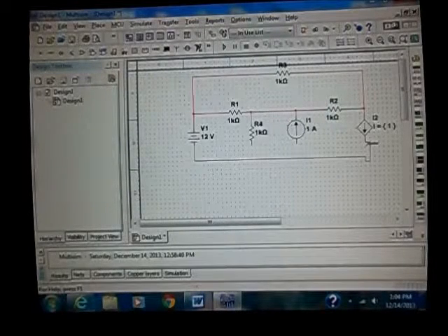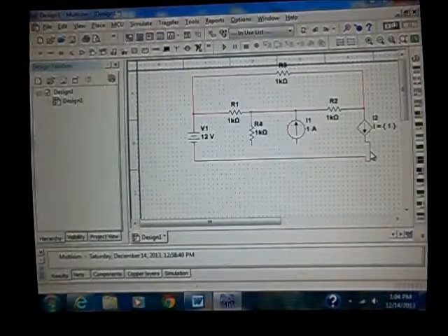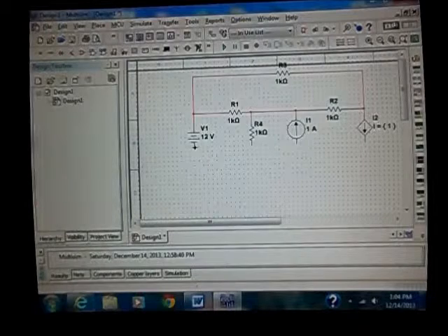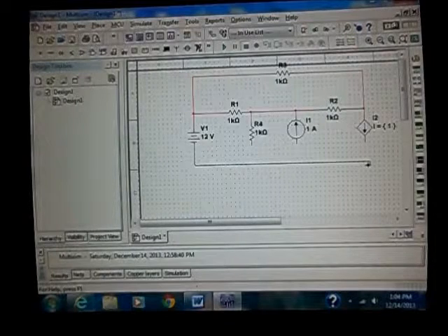Oh, well, that didn't look so good, did it? So whenever you have an error like this, I'm going to click on that wire that I don't like because it got ugly, and do it again. Sometimes that happens. Let up, press down, and I want to stop right there. You don't always have to let up and press down; sometimes it bends where you want it to. And then don't forget to click when you get it to its destination to actually connect the wire with a little connection dot, as you can see.